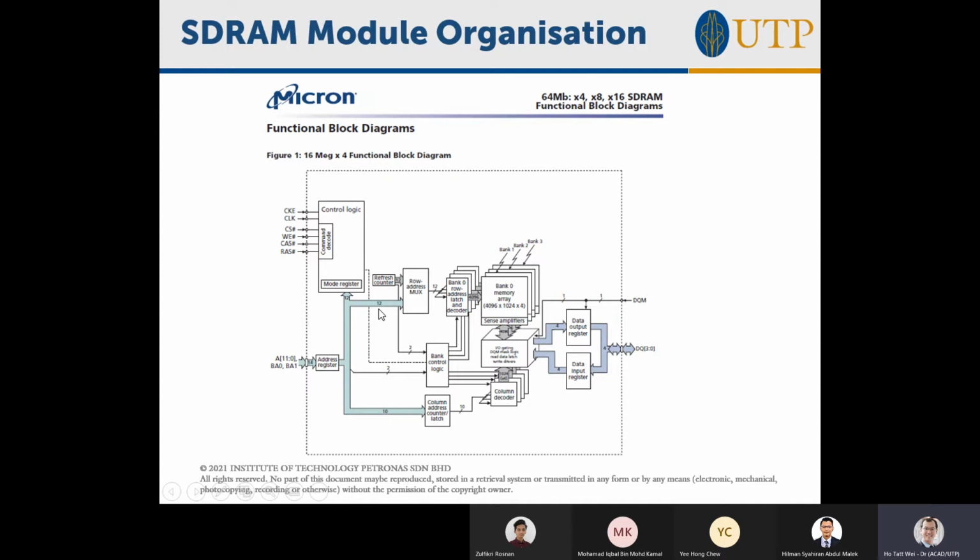To the power of 12, there are 4096 rows. That means the bit line actually has 4096 transistors and capacitors attached to it, and the word line has 1024 transistors attached to it. That's how many it is, and it's very long and has a lot of capacitance on it. So beyond that size, you're not going to find a very large block.